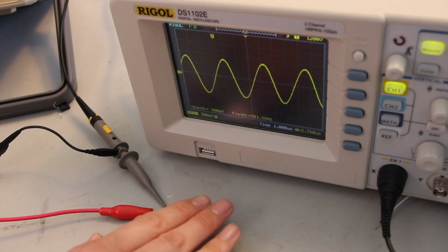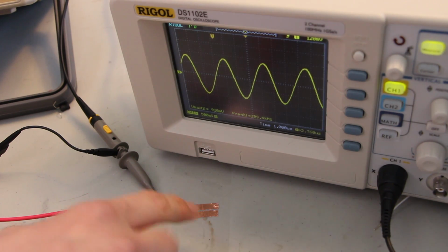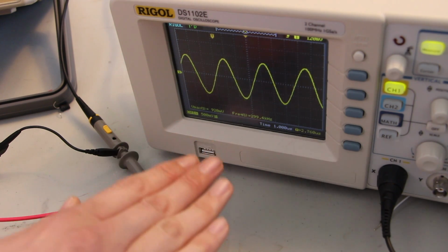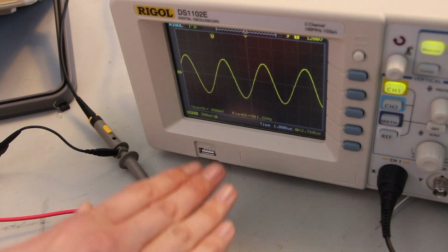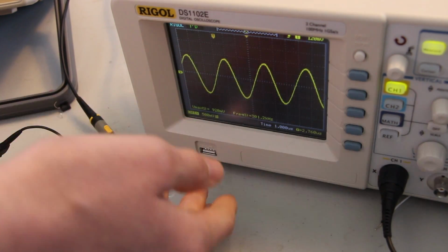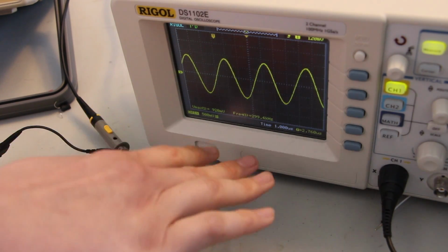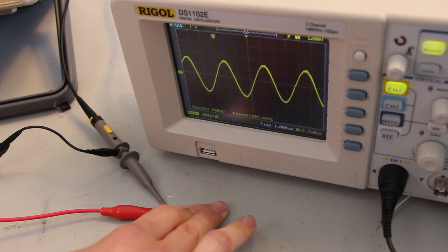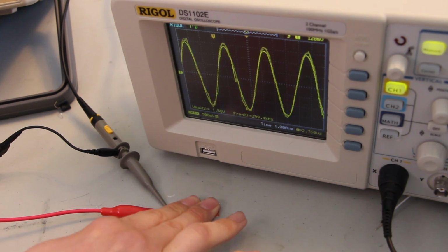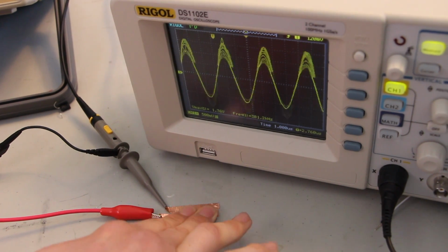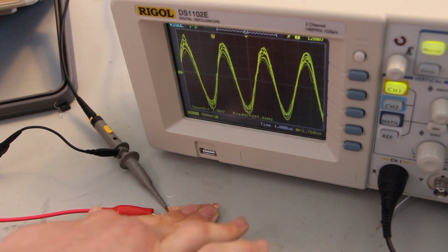Then there's a much more subtle effect where some of the signal that would just naturally go through the air from one electrode to the other gets absorbed by my body as I get close to it. But the effect is very nonlinear with distance, and it can be unreliable to detect hovering above a touchscreen using this very small change. So usually touchscreen controllers are just looking for this very drastic change when your fingers are right on the glass that's coated with the transparent electrodes on the backside.